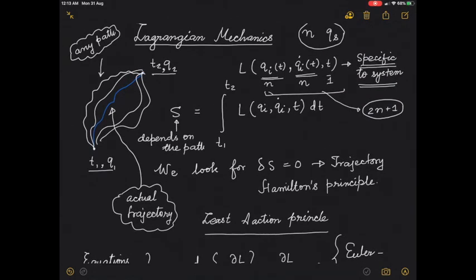Right? Now you see, in the case of D'Alembert's principle, we had delta W equals 0, and we wrote it with a delta because that work done corresponds to a virtual displacement. So here I write delta for what we call the variation of the path. If you go through the previous lecture once more after hearing what I'm going to tell you now, you can convince yourself that these variations of different paths are actually the virtual displacements that we were talking about earlier.